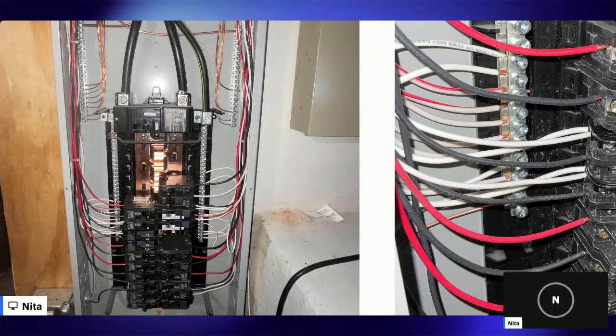Sometimes, like I'm thinking about the house where I've routinely gone back to, and when I'm just being walked around, that cabinet, that stuff faded. You can't see it, it's peeling off. That's the defect. The circuits must be clearly and properly labeled. If not, that is a reportable defect. Because if you had an issue and you needed to kill the power, how would you know which one to kill? You would have to kill them all.